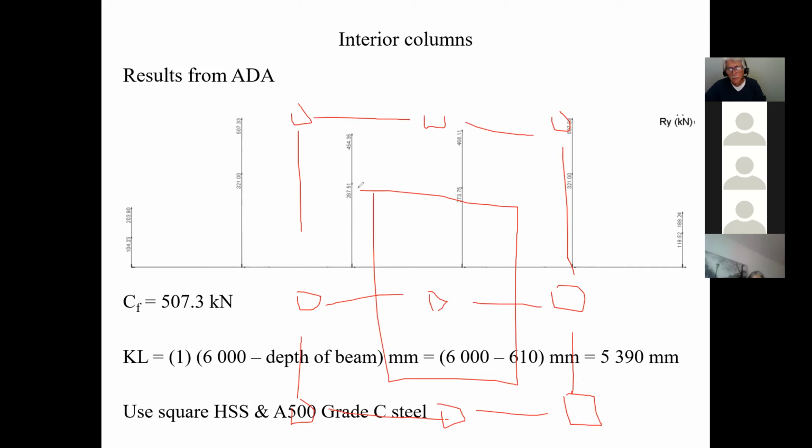No, because it passes over the column. Exactly. And that's going to affect how the CF is going to go into the column. So keep in mind, this way of calculating tributary areas is only valid for things that are simply supported.